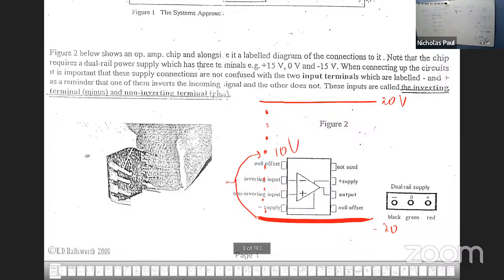So you're connecting at minus 20 and you're connecting at 10. What do you think is the total supply? What do you think is the total voltage I gathered in? Minus 10? Okay. If you connect 20 to minus 20, zero. So you're not getting nothing then. You'll get 20 volts. 40 volts, right? Because the potential difference is the higher minus the lower. So 40 volts become available, right?